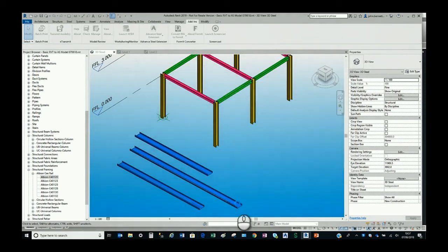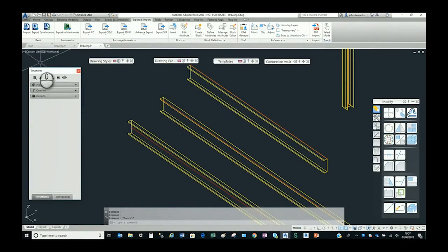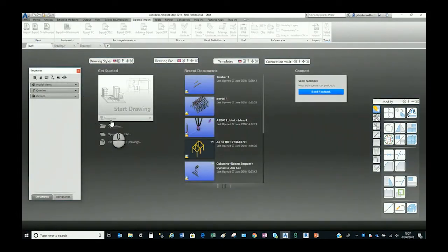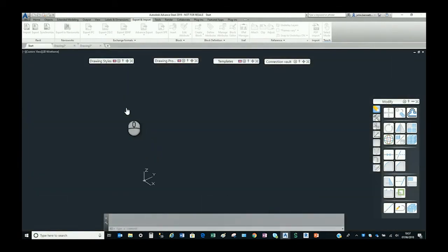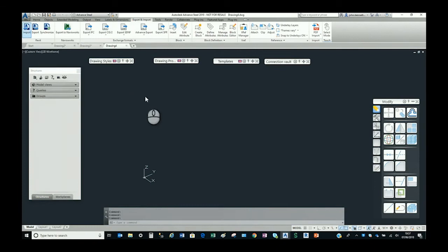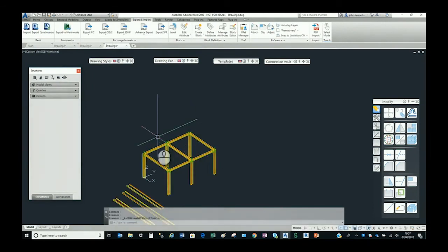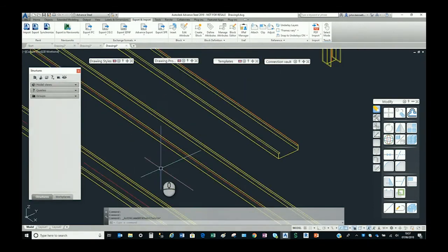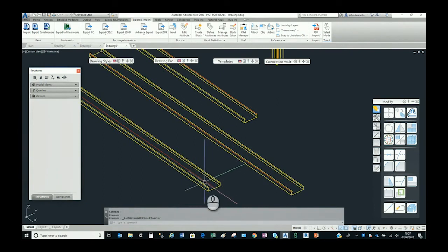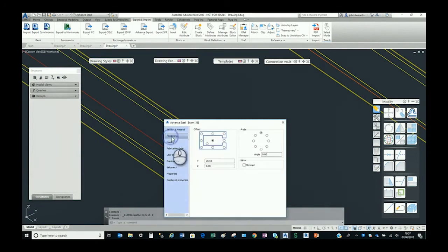So with the dynamic setting this time, come back to Advanced Steel, pop in and create a new file quickly, and then import again using the new file that I just created with the dynamic setting. And we can see that's come in. It's respected the positional data, the system line position. Okay, the things are rotated around the right direction.